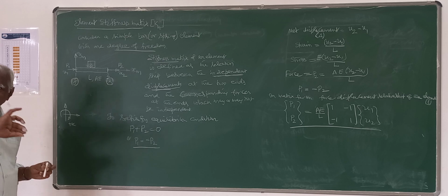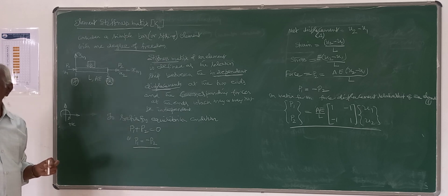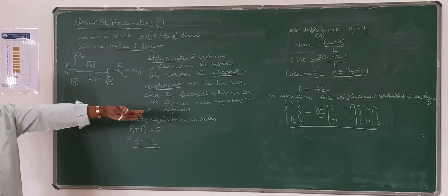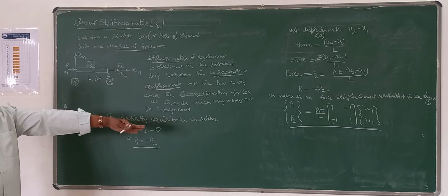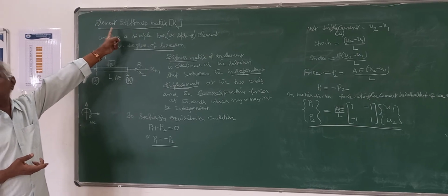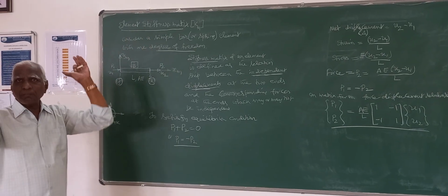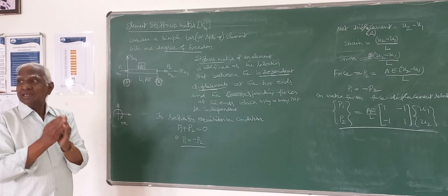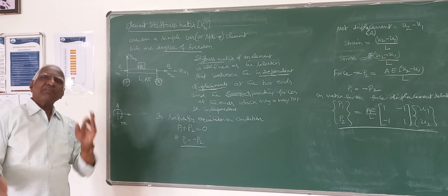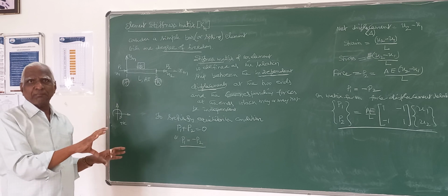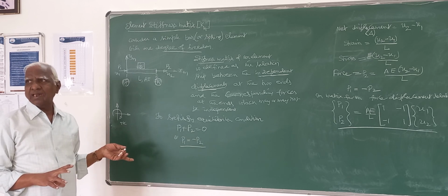Like that, for a simple plane truss element, simple beam element, simple rigid plane frame element, space stress element, we can derive a relationship like this. That is called the member stiffness matrix or element stiffness matrix. That's a property associated only with the elements. Then our loads are all in the global direction, we relate them. So that is the basic concept of our matrix structural analysis.